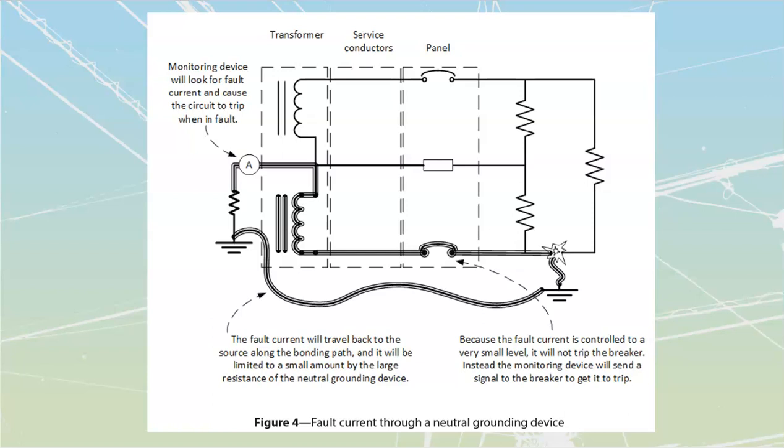This is now a different fault path where I want to restrict the amount of current. Rather than getting 5 times, that's my target value, 5 times the current that should flow through that circuit. I mean, if this was a 100 amp, we would want to have 500 amps flow through that circuit. Underground fault, sometimes that would be too much current. It would be damaging to our systems itself.